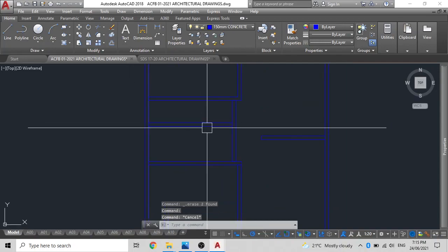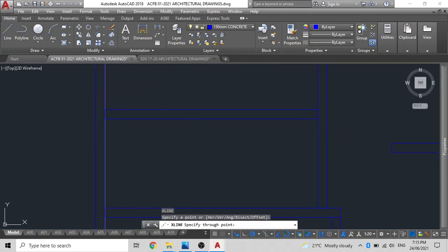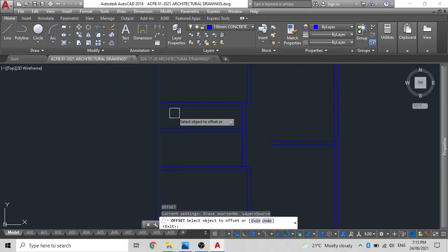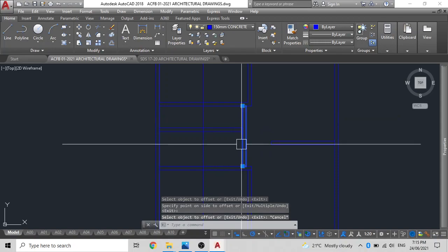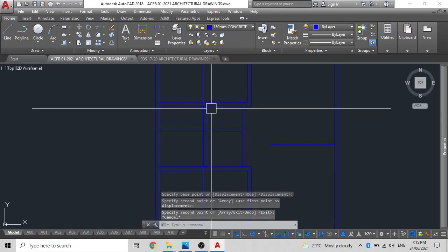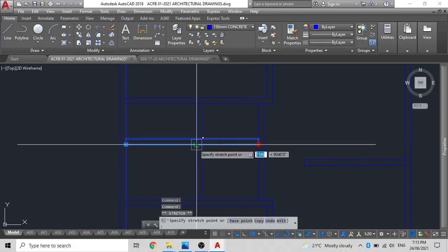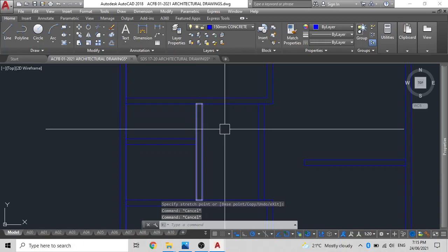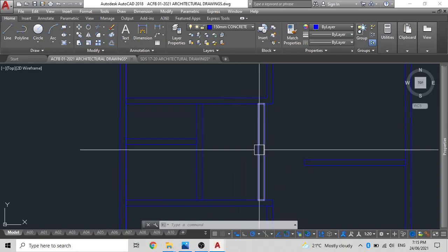What you can do now is simply create another wall here. Offset this X line to a distance of 1.8 meters. Then create another wall here. Just copy this and paste it over here. So what that does is this will create a barrier between these two, washroom and the bathroom, and you'll also have a door area and an area to hang your door and things. And this space in the middle can be your vanity, where you can come up and do your toothbrushing etc.